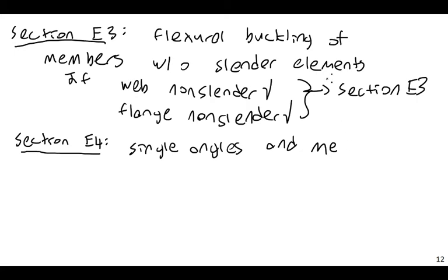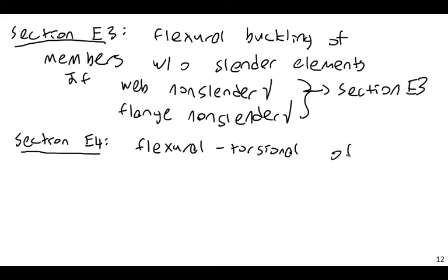Well, I guess this is just another buckling mode. This is just flexural torsional buckling. Sorry, we haven't talked about that yet. We will talk about that next time. It's a more advanced buckling mode. So again, flexural torsional buckling of single angles and members without slender elements.